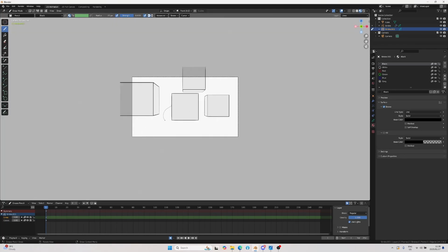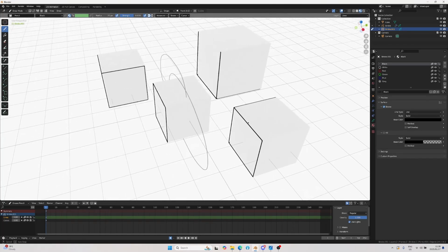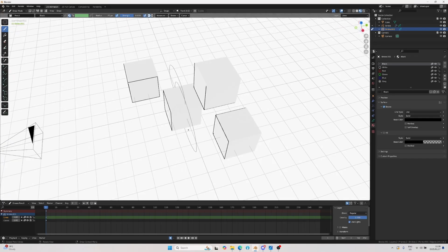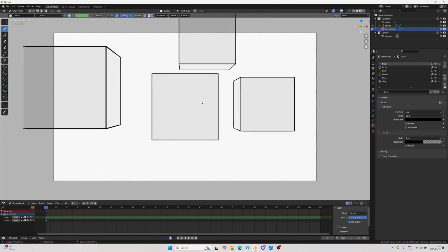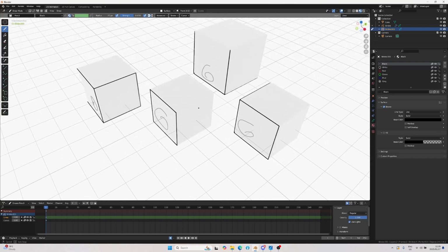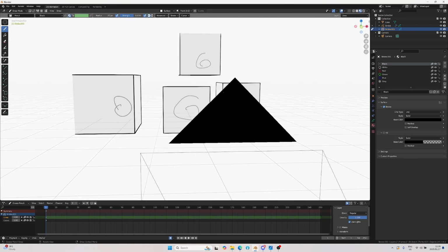So if I'm doing my drawing here, you can see it's happening right in the middle of world space, at the middle of the axes here. But you can choose surface. So if you're doing a 3D, 2D integrated workflow, now what's going to happen is I can draw anywhere on 3D objects and it'll be in the surface of those objects.